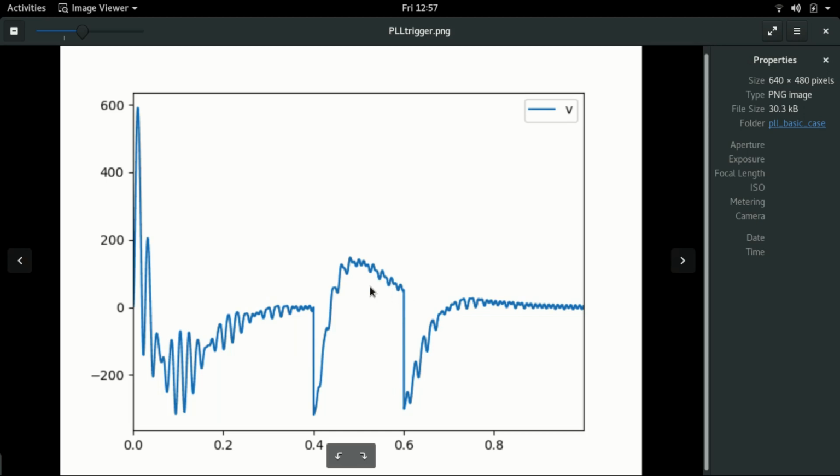Now, if you do notice, even though our frequency seems to have settled, the trigger voltage has not yet come to that. Trigger voltage still needs a little more time, right? So really speaking, a trigger voltage will only settle in 0.3 or maybe more, right? Now, the question again here is, is it something that you want to settle? Is this something that you want to correct, or is it something that you're okay with? Because remember, 0.2 seconds corresponds to around 10 cycles, right? So which means when there is an event, and this is a jump in frequency.